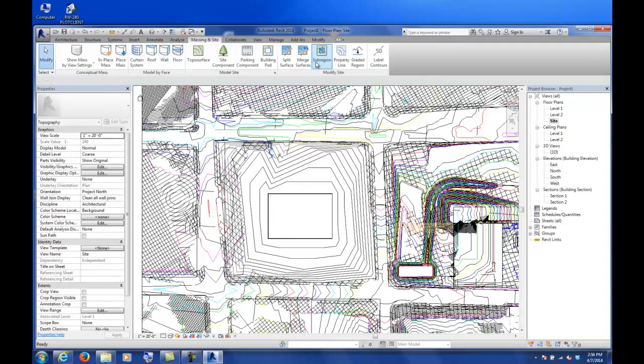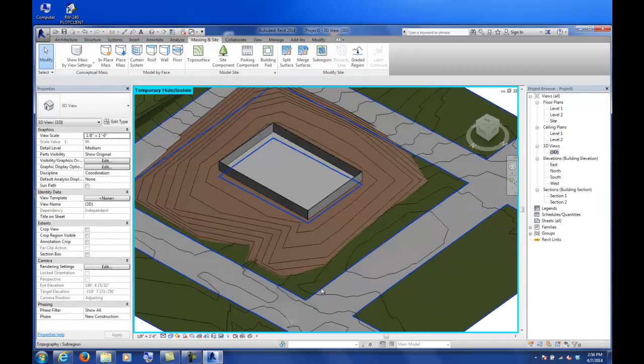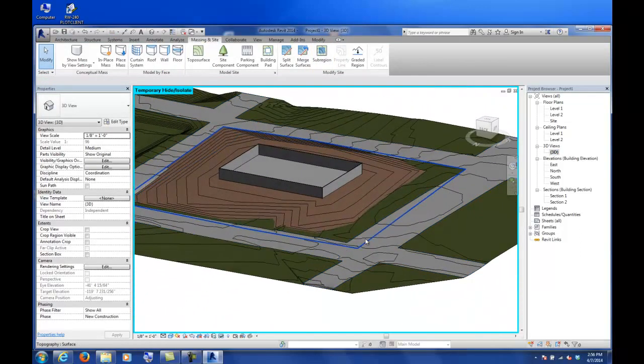And when you're done and you hit the checkbox, I've now got that surface that is intersecting with the other. And if you make it where the end of your surface is well below the rest of the topography, then it'll start to show you exactly where the intersections are between the two topo surfaces.